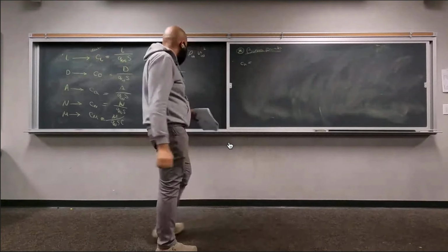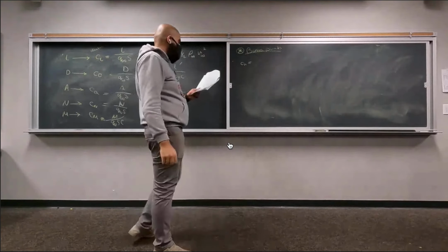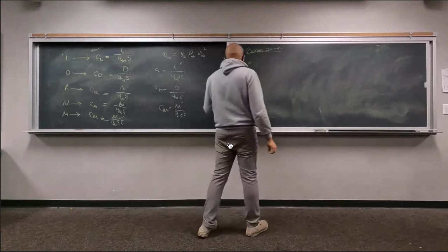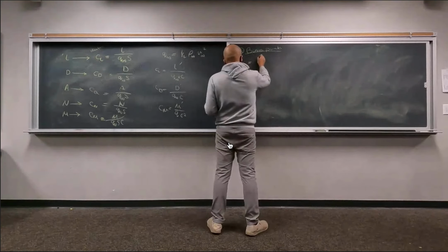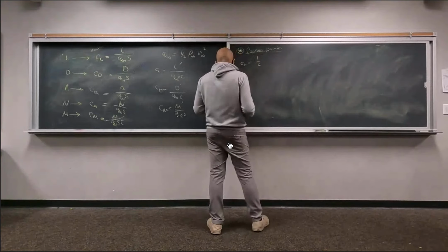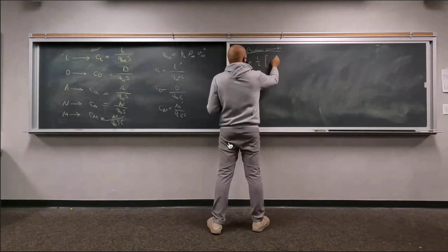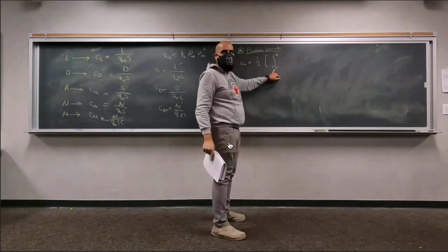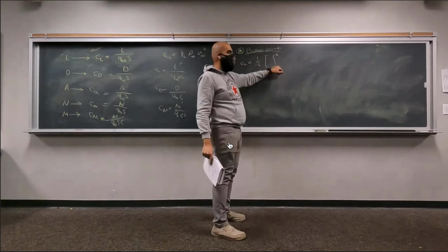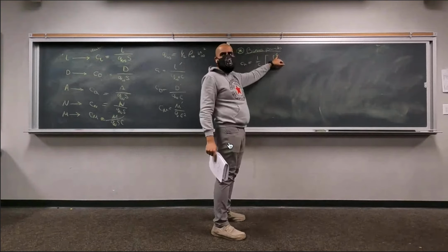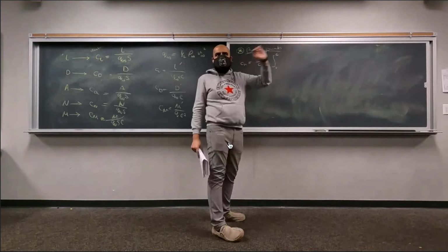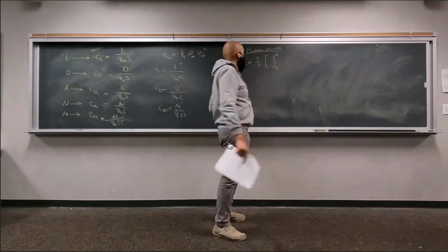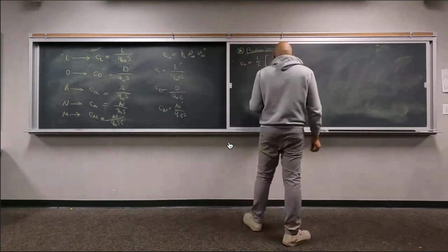So your normal force coefficient can be calculated, and this is per unit span again. The integral from 0 to C. 0 is the location at the leading edge. At the trailing edge, your location is going to be the chord length. That's the maximum length you're going to see on the wing.